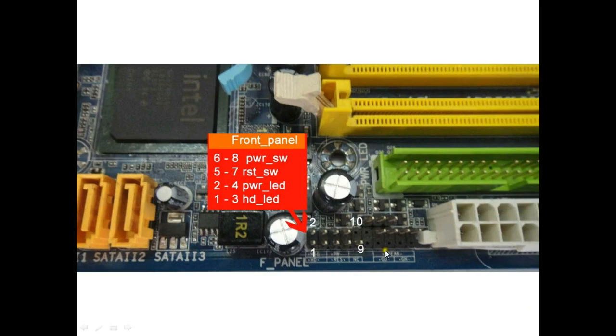And here comes the front panel connector. To the front panel connector, we connect the power switch, the reset switch, power LED and hard disk LED. The front panel connector has a total of 10 pins, but the 10th pin is the no connection or dummy pin. The pin that is diagonally opposite to the 10th pin is 1. The pin counting is like this: 1, 2, 3, 4, 5, 6, 7, 8, 9, 10.